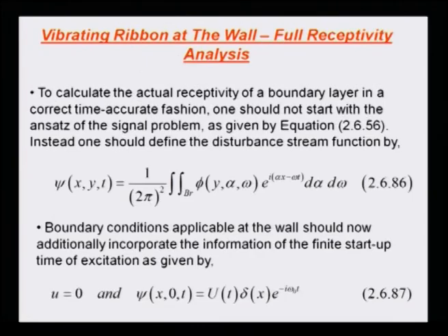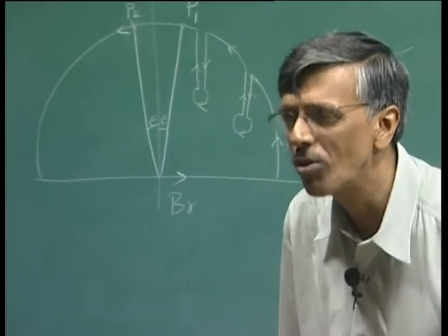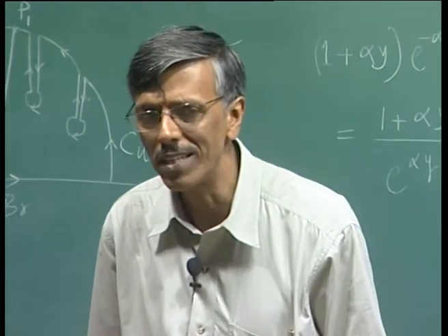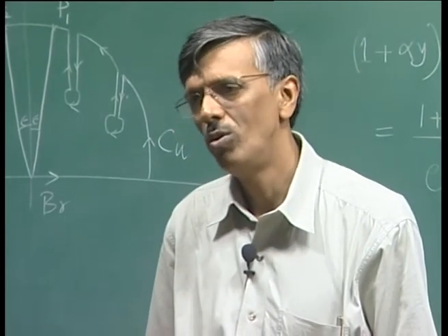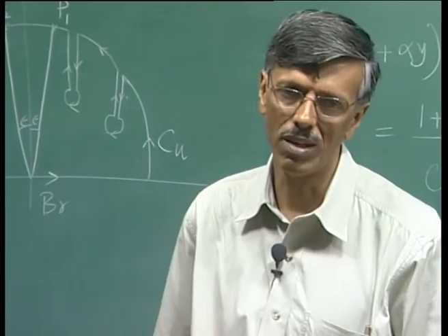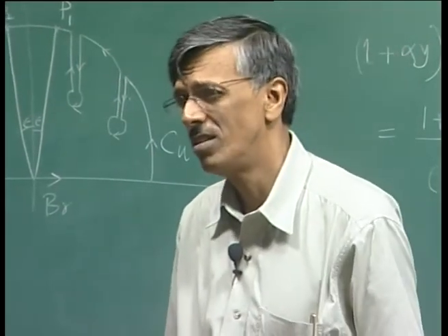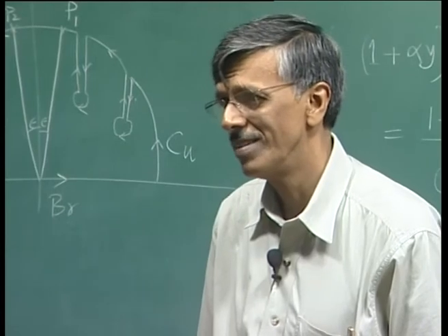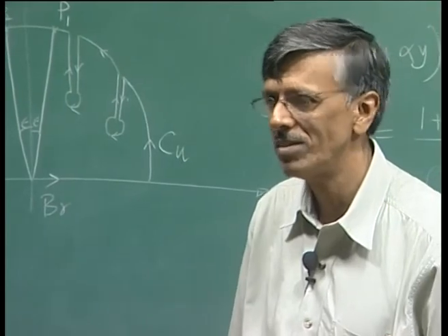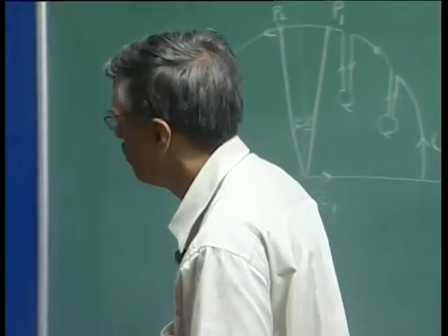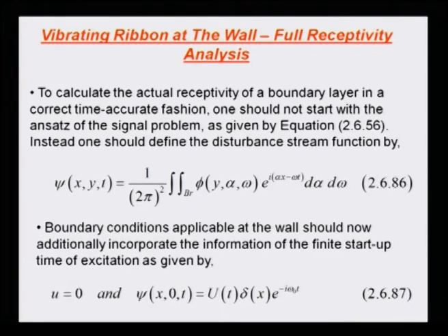Now, so far what we have done is we have talked about the so-called signal problem. We excited the fluid dynamical system at a frequency omega naught. We also got the response at omega naught. That was our assumption. Suppose we don't make that assumption. So instead of doing a Bromwich contour integral in the alpha plane alone, suppose we go and explore the full receptivity analysis. We don't make any assumption of the signal problem.